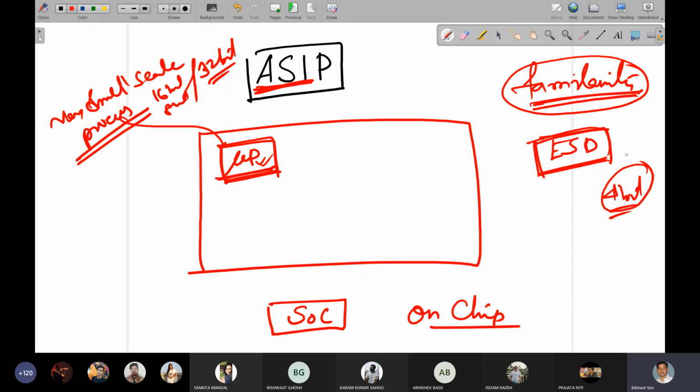So you should be familiar, and you may be thinking of some microprocessor which is still not available in the market and will come very soon. Don't design your embedded system based on future applications or future AI-based applications. Whatever microprocessors are available in the market, based on a familiar microprocessor that you are habituated to, you should start the design. This is a very critical experience we faced during design. Don't think, sir, if we have a 16-bit, it will be better. Don't think in this way. Whatever you have, within this you try to design. Clear? So the microprocessor will be there.